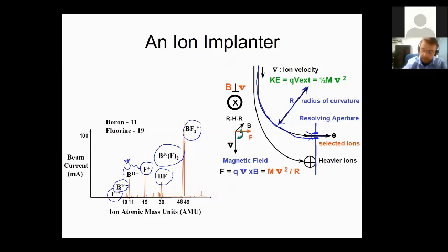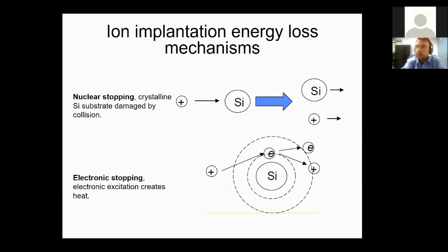And the other ones, the heavier ones, its mass will increase. See, in this simple equation, it's the Lorentz force equating to the centrifugal force, if you're familiar. If not, that's not too critical, but what's happening is the R, if you take it out to the other side, is proportional to the mass. So the radius, the trajectory can be predicted. And you can filter out these heavier ions. You can make sure that they won't go and infiltrate into your silicon surface.